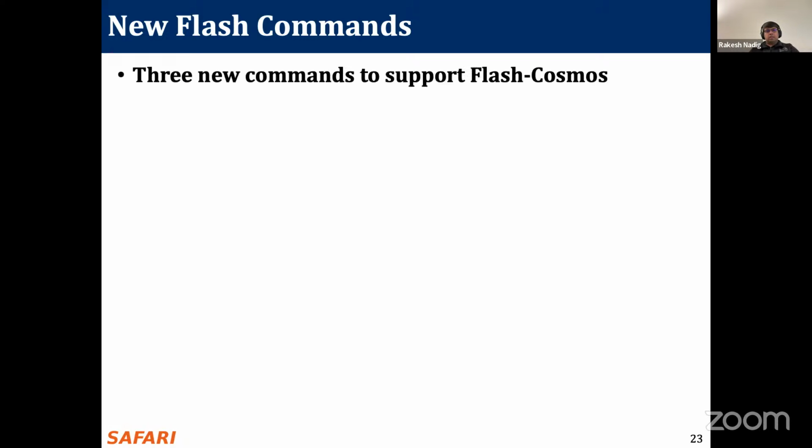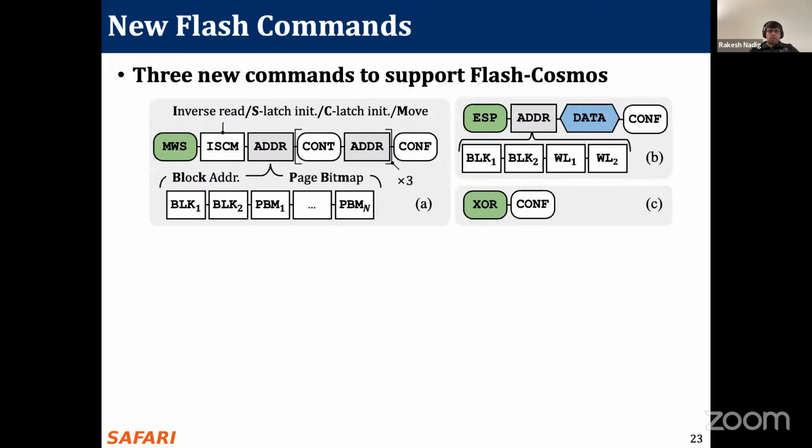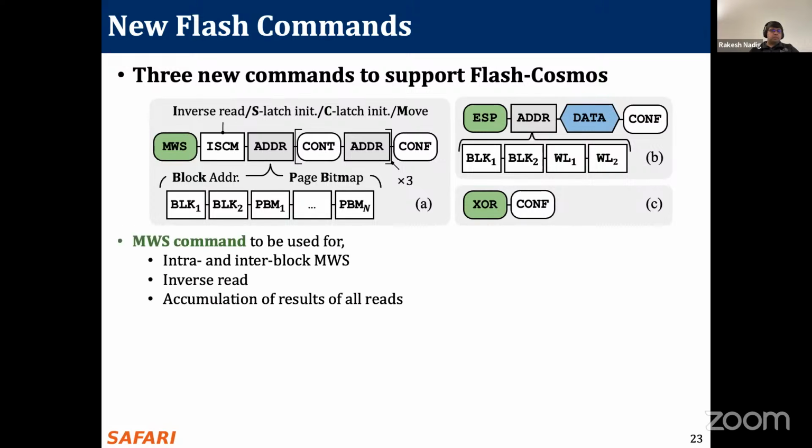We support 3 new flash commands for Flash Cosmos. The first one is called the MWS command, which is used for intra-block and inter-block MWS. It also provides support for the inverse read operation and accumulation of the results of all the reads.